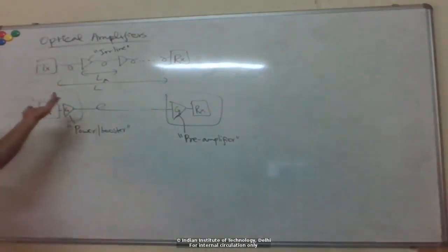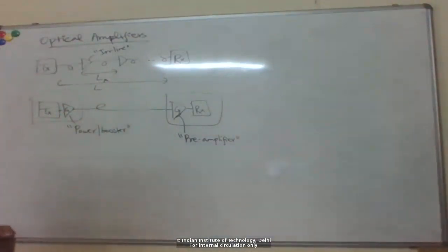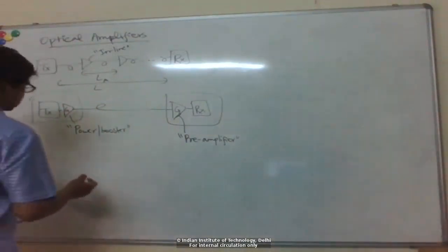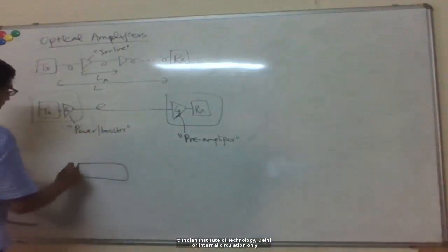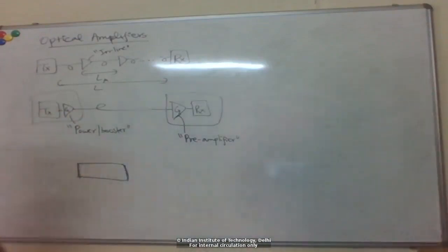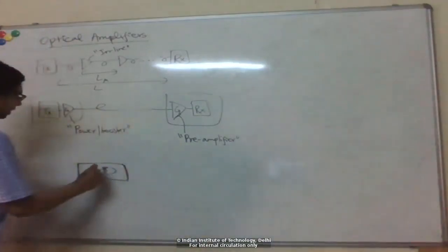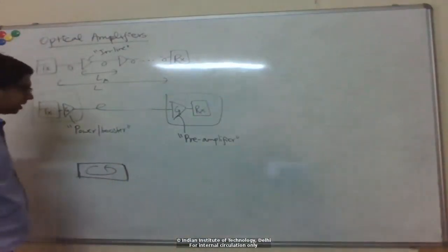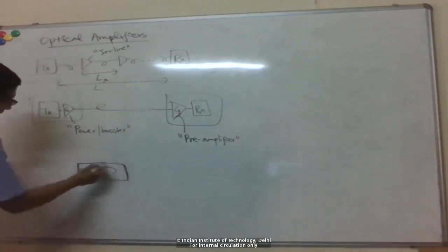Okay, and what is an optical amplifier? We've discussed already optical sources and specifically lasers, right? And you know what a laser was: basically a gain medium formed between two reflecting ends, which formed a cavity, right? And we had gain in the middle due to population inversion. So an amplifier is basically a gain medium without this optical cavity.